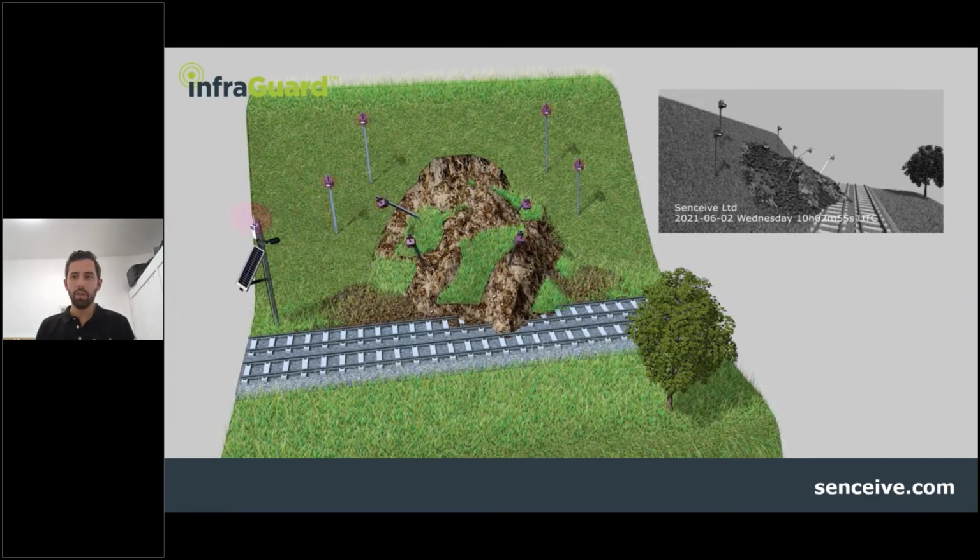So this video's animation we have right now is, of course, on a cutting, doing slope stability type monitoring. You can imagine those other application areas that I summarized earlier where this technology could certainly be used. Essentially what we're doing here is monitoring something long-term with very low maintenance, low power, long life sensors, and capturing movement at the point of when it does occur and communicating that through to a user with that data and with that visual verification.